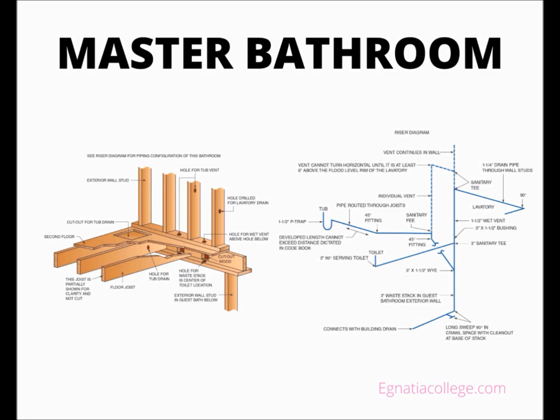Exterior walls that have a 3 inch waste stack might have to be constructed with 2x6 wall studs instead of 2x4 studs to accommodate the 3 inch pipe and fittings. If a 2x4 wall is constructed, a plumber might have to find an alternative pipe route because he or she might not be allowed to cut the outside band joist enough for the 3 inch sanitary tee to be installed. An alternative would be to install the vertical piping in the interior wall of the stairwell, because the piping could still be routed in the direction of the second floor joists.